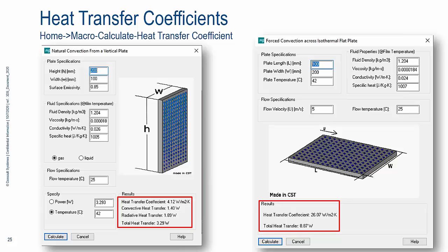And if you take a closer look at the one on the right, the radiative heat transfer, which is the second value on the right earlier, is almost the same, or in this case slightly bigger than the convection one. So this is the key. If you're modeling something in natural convection, which means there's no active cooling devices involved, you must model radiation.